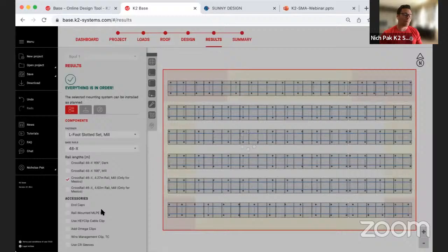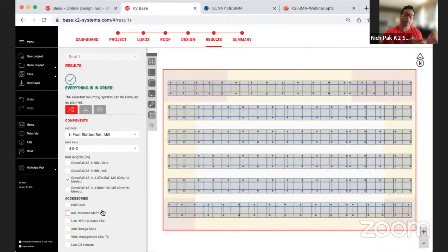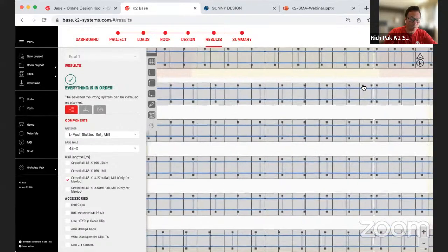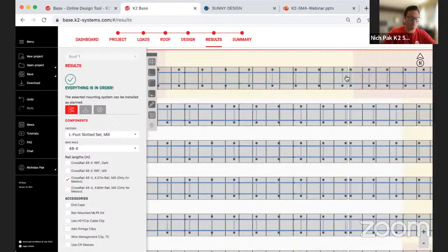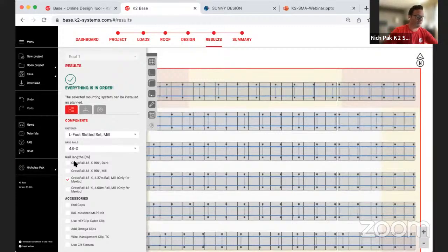Here is a small top-down view and breakdown of the engineering of the racking system underneath it. So you'll see here that we have our rear leg and our perpendicular leg that's going down the array. And then of course we run these rails horizontally. Here's that thermal gap that I was talking about. So we're going to break the rail right here in the middle, so the array can be separated from itself. So it has the ability to basically contort and not have to pull and stress on the structure too much. Let's go to selecting equipment here.